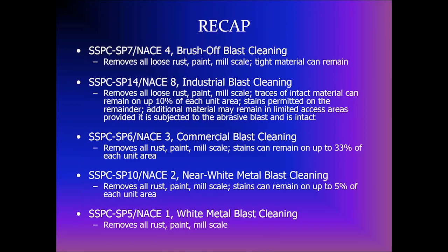So as a quick recap before we move to the visual standards, SP7 brush-off blast cleaning removes all loose material, anything tight can remain. SP14 industrial blast cleaning removes the loose material everywhere, but tight material can remain on up to 10% of each unit area. Stains permitted on the rest of the surface. And in limited access areas, the 10% restriction doesn't apply, provided those areas have been subjected to the abrasive blast and the coating's intact.